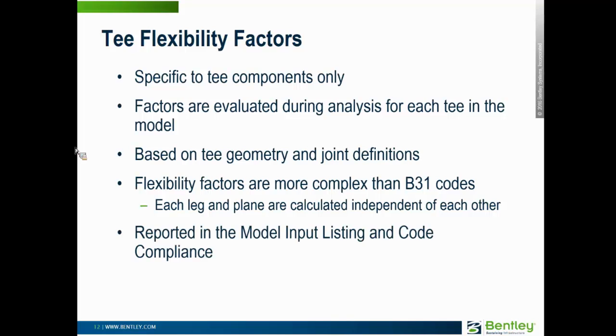Also, all of these T flexibility factors that are evaluated in AutoPIPE will be reported as their actual factors in the model input listing, and the code compliance will reflect the changes in the stress reports. And I'll show that in an example demonstration here shortly.